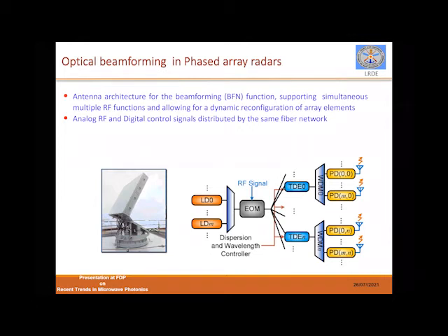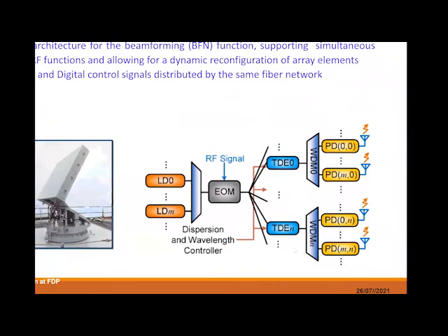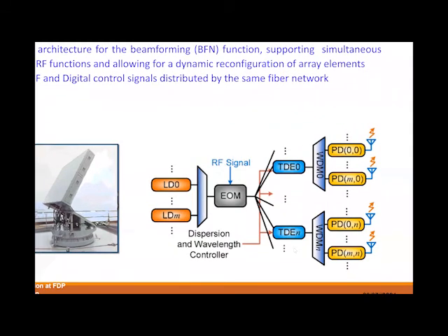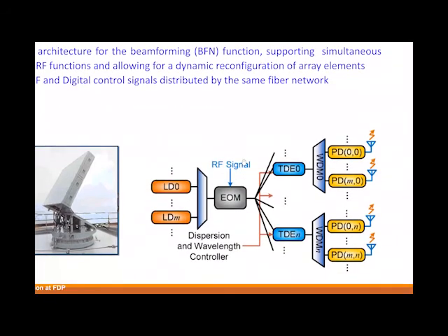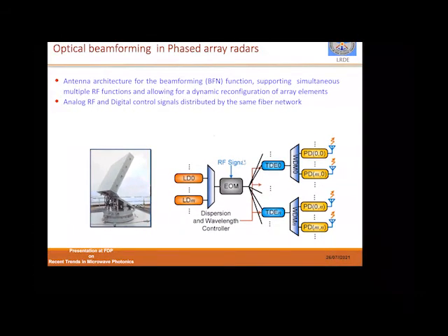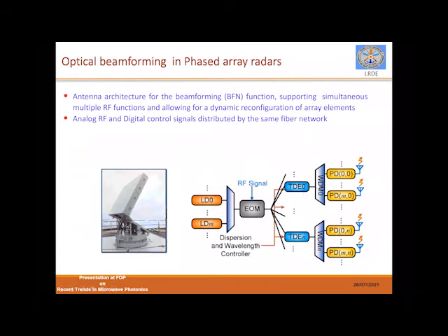So in that case, you generate the signal, and then give the time delay according to your element position and combine them, and finally it is converted back to the RF domain after forming the beam. If you do that, this beam squint effect will not be there.